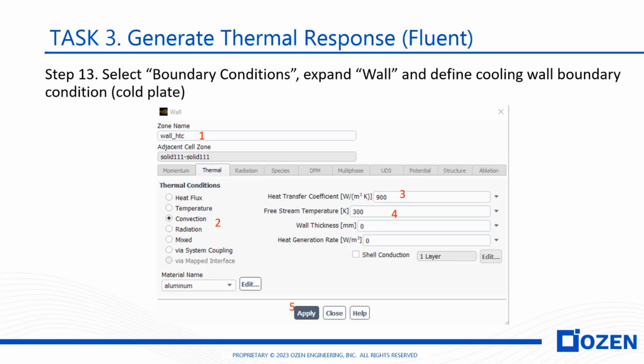All right. So once all the materials are defined and assigned, back to cell zones, another key aspect of CFD simulation is setting up boundary conditions. And here, I'm just going to show only one example. Most likely, there are other boundary conditions at the wall. They could be adiabatic, or they could be fixed temperature.